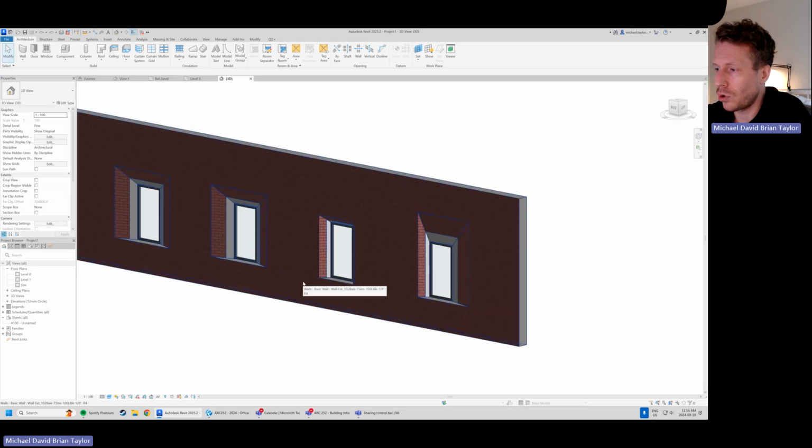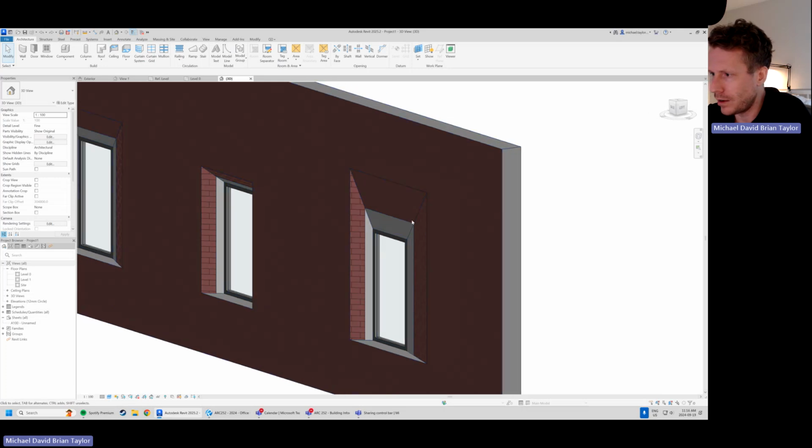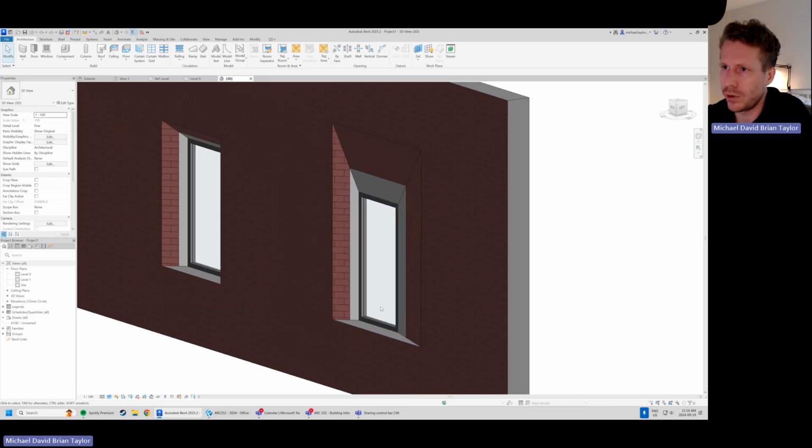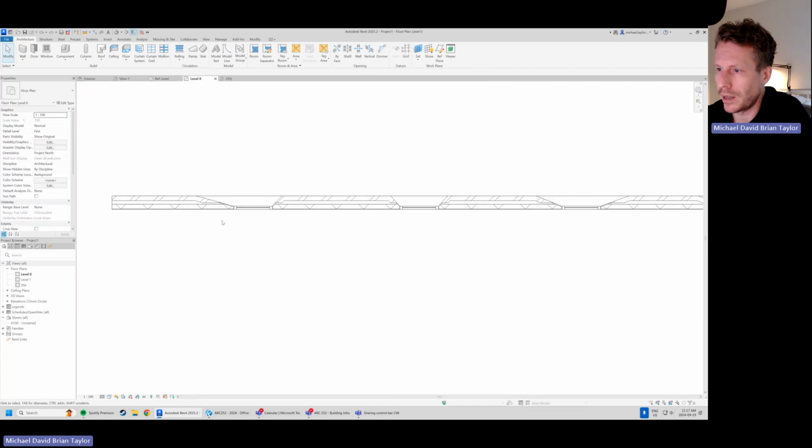Let's jump back in. There might be something here that we notice that maybe isn't so hot. If we jump to the plan view, we've got some challenges with the way that the actual software is seeing our wrap. This really means to me that maybe our frame isn't deep enough, or that the reference plane for our interior offset is too deep in the wall and needs to come out a little bit. If we jump to the plan view, it should be pretty evident here.